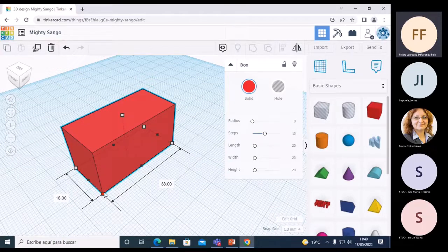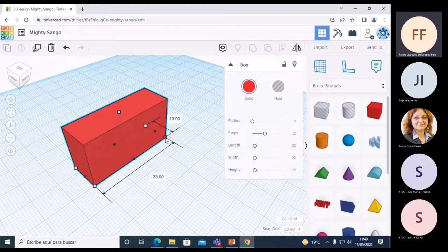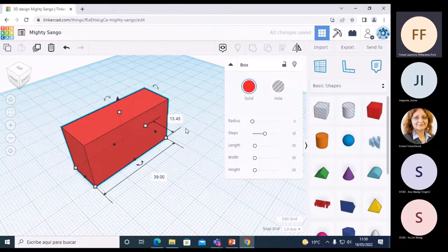So basically, all objects can be made smaller or larger with these handles. And if you check the label, TinkerCAD uses dimensions with 2 digits. So if we do not have exactly integer numbers in the dimensions, so not exactly in millimeters, you can click on the label and type different real numbers here with 2 digits, and you can define the dimensions very precisely.